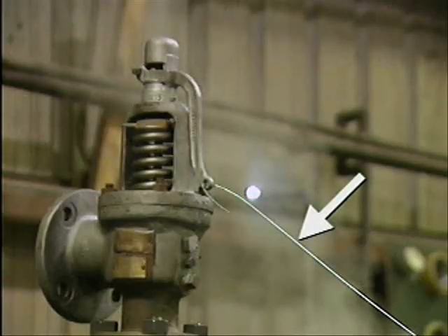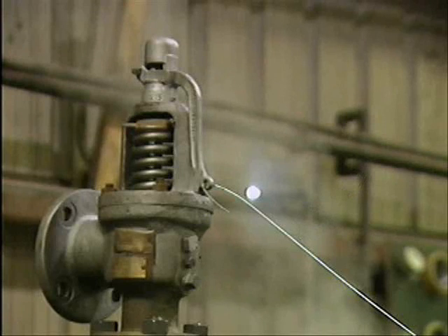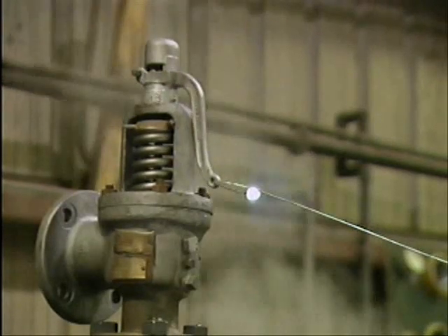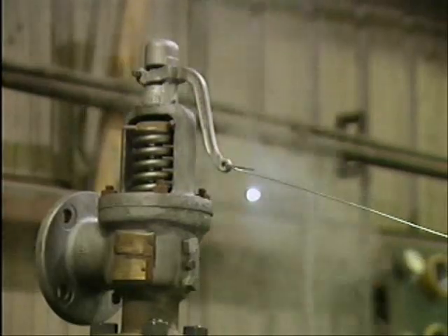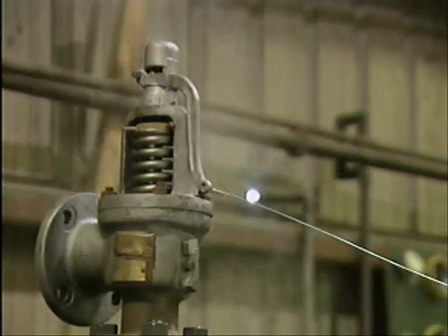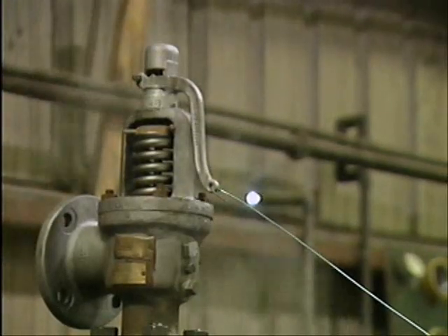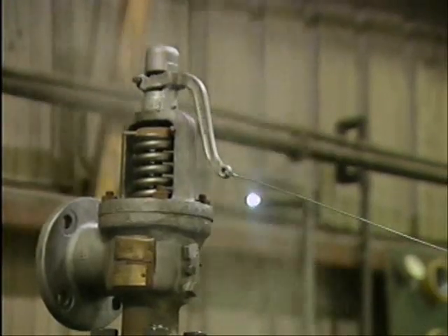Attaching a hook to the valve's release lever enables you to position yourself as far away from the valve as possible. This is important because when you hand lift the valve, a great deal of hot, pressurized fluid could be released. To lift the valve, pull the hook hard enough to open the valve all the way. You should hold the valve open for only 2 or 3 seconds. If you hold it open any longer, the disc could be damaged by the rush of steam.